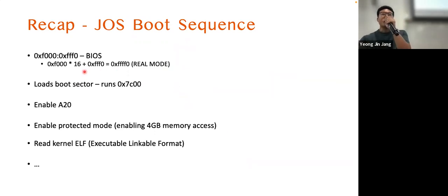We learned about real mode segmentation. The segmentation is required because the old-day CPUs only have 16-bit registers. So we need two 16-bit registers to indicate 20-bit addresses. And to do that, it has a very easy calculation. There is a segment and offset pair.